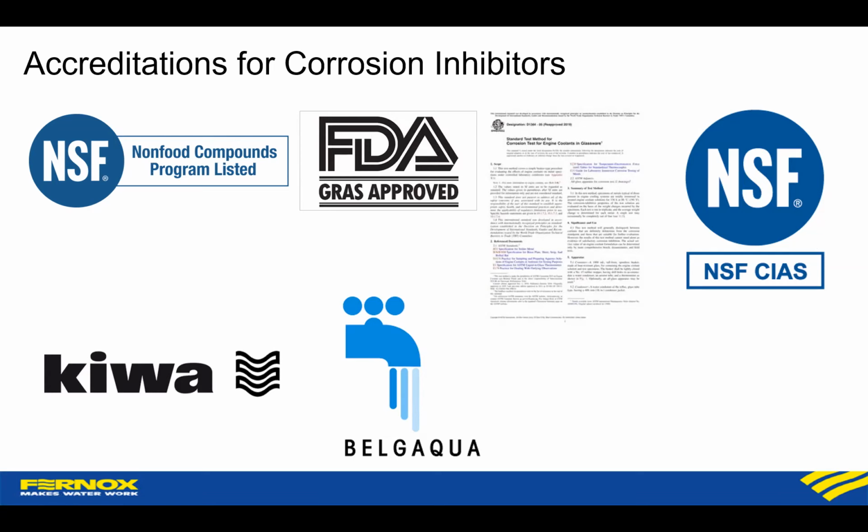So we try and mimic that as much as possible. We've also got a couple of materials that we test, non-metallic tests. So we also check rubbers, EPDM rubbers, and O-ring material to make sure that the chemicals don't swell or perish in those.